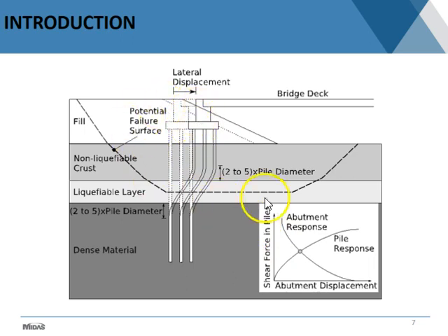Now, on the other hand, from the point of view of the slope or the abutment structure, as you have a restraining force that is larger and larger, the expected amount of displacement that this system is going to have is going to get reduced. So you can think of it like an external load that is going to restrain the movement of this system, that as this force goes up, the displacement that you're going to have is going to get reduced. This is a decoupled behavior, one coming from the slope/abutment and the other one coming from the piles.